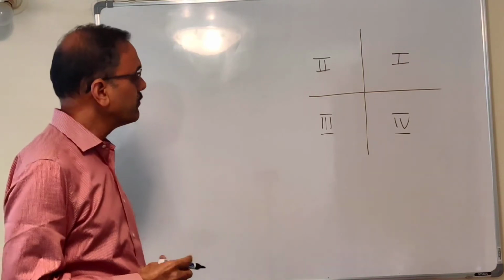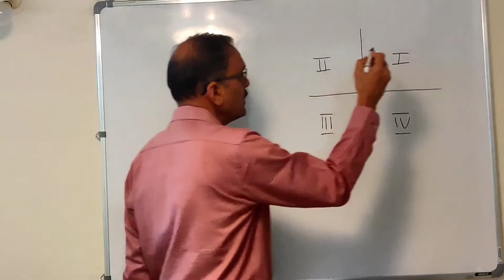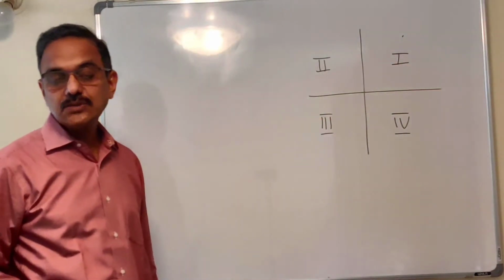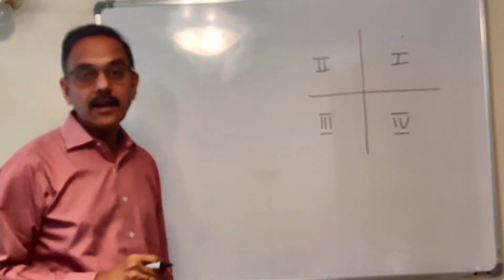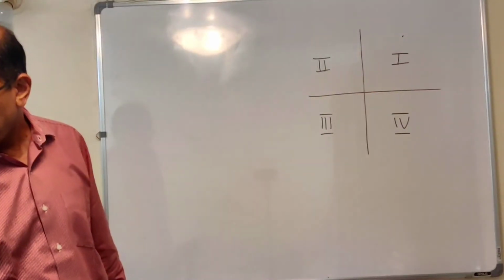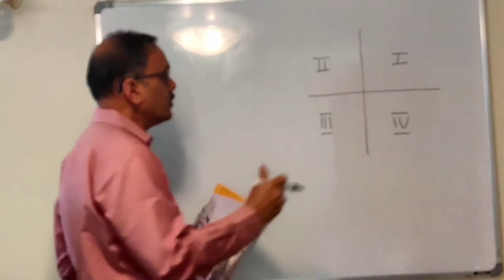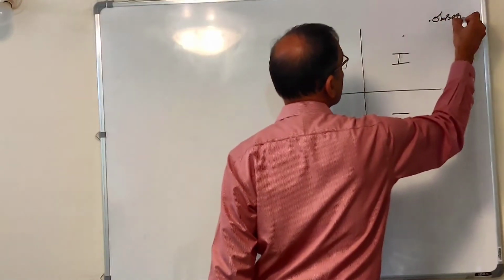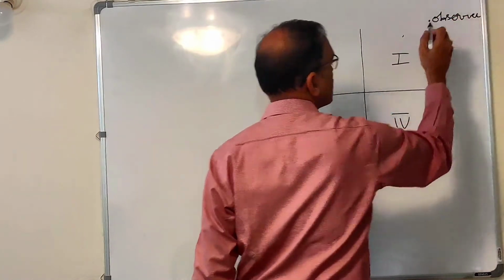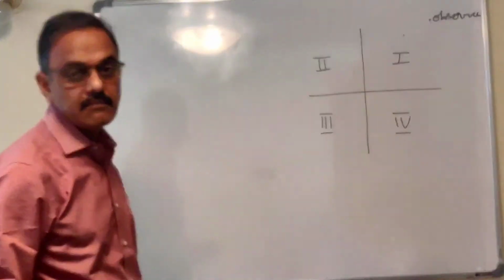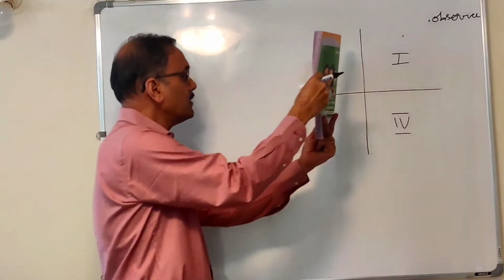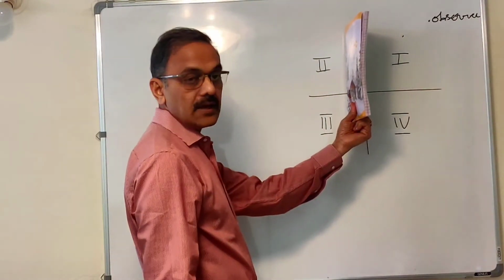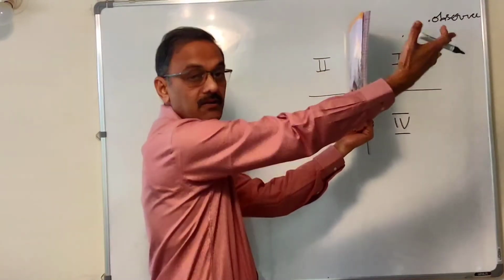Now if there is a point in the first quadrant here, can you tell me what is its position with reference to VP and HP? Imagine the observer to be in the first quadrant always. The observer position is here. So when you have a point in the first quadrant, for the position of the observer, I can say the point is in front of VP.